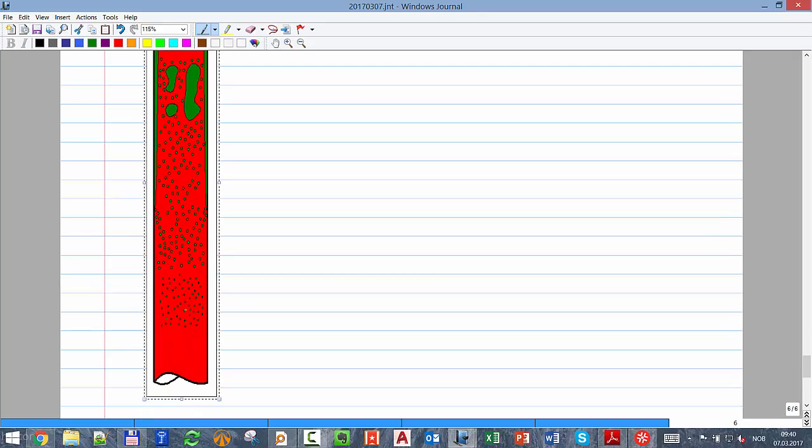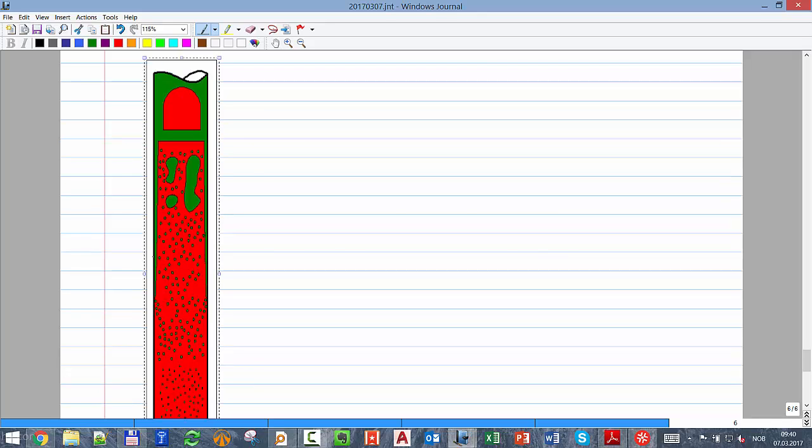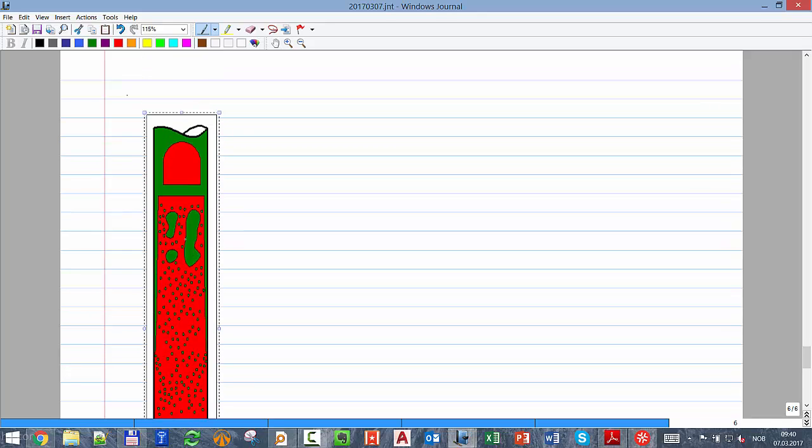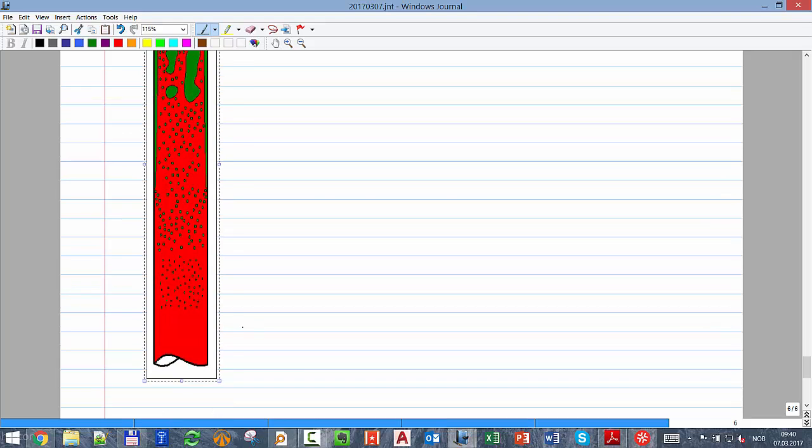Okay, again I have pure gas, some mist flow, then that mist starts to stick on the walls, then at the end starts almost blocking the pipe, and at the end I have just the same slug flow that I had before. So in gas that's called mist flow.